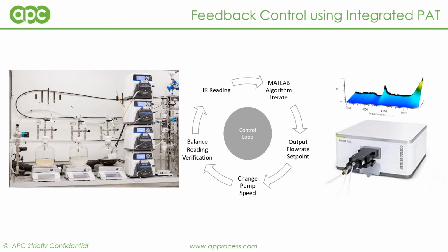and the balances to iControl, where a simple feedback control loop was created through the data link tool in Excel. We used basic logic statements such as, if X is greater than Y, then increase the flow rates by Z. Unfortunately, this initial approach, however successful it was, could only be used to control one feed stream, and we wanted to control 2 out of 3 feeds active here. So we had to build out a little more sophistication facilitated by moving to MATLAB.